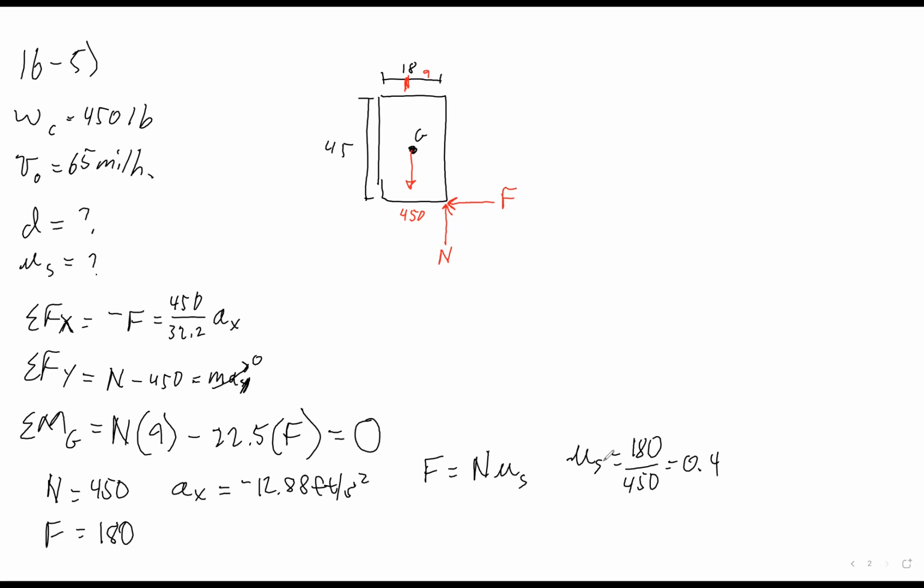So we're kind of working the problem in the wrong order here. But what we need is a relationship between the velocity and the position of the truck. Since we know the acceleration, we can use the chain rule to create a version of acceleration that is a function of velocity and position.